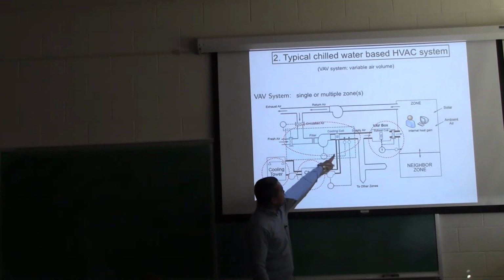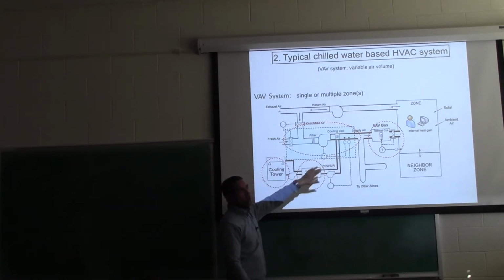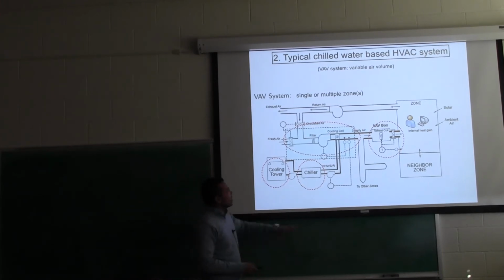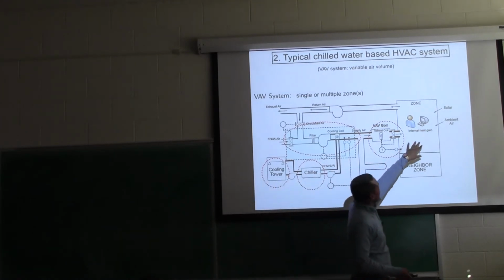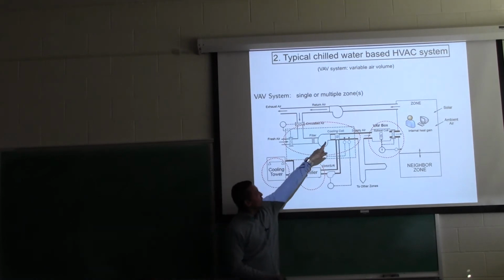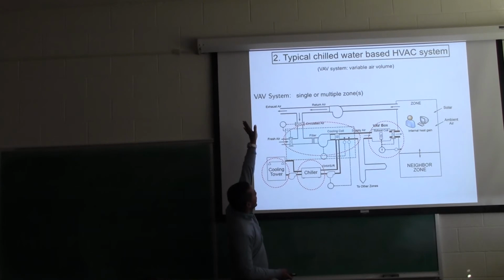The water comes into the building into something called an air handling unit. I don't know how many air handling units there are in this building, probably 5 or 6, or maybe 2 or 3, depending on the size. The air handling unit is basically a giant air conditioner. A fan pulls the air out of the building and it's ejected outside, but not all of it.